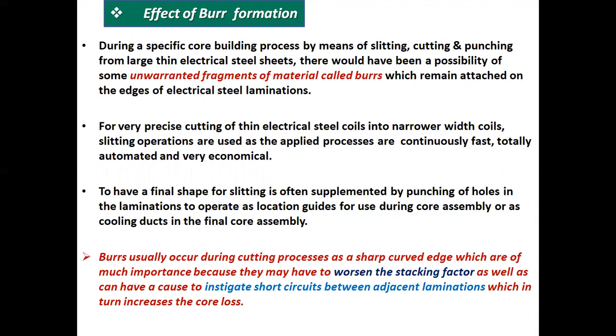as the applied processes are continuously fast, totally automated, and very economical. To have a final shape, slitting is often supplemented by punching of holes in the laminations to operate as location guides for use during core assembly or as cooling ducts in the final core assembly.